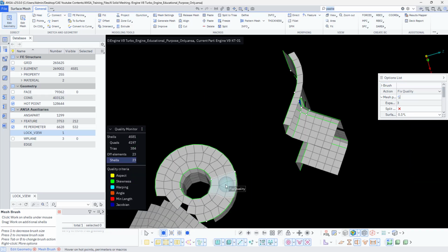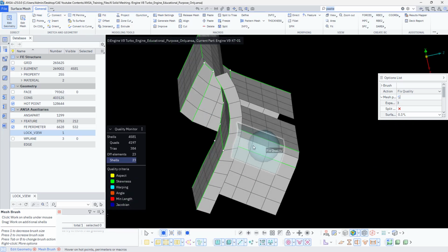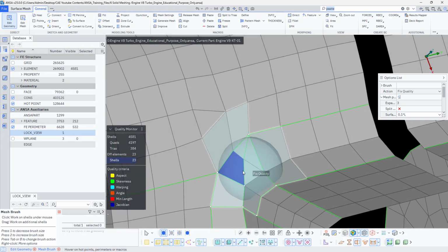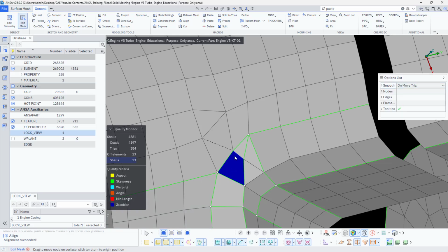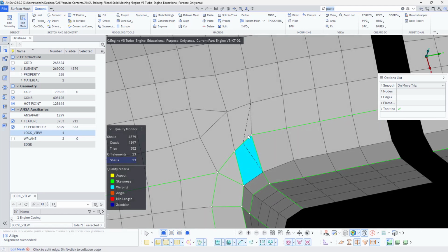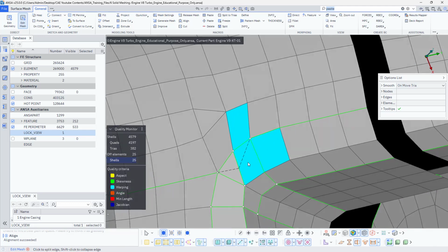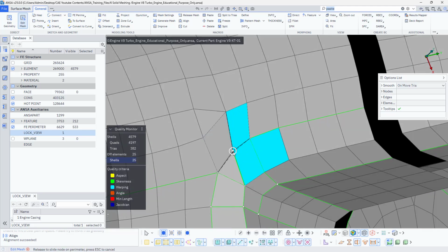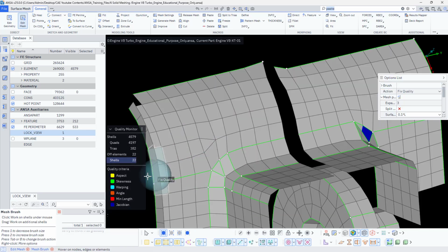Actually, yeah. Here, in this case also, best would be join these two, remove this edge, and here the warp edge. Sometimes we won't keep actually warp edge, so if you remove it, that would be great also. Means I'm just helping you guys to deal with all the kinds of the mesh criteria. Some people simply keep them. Aspect ratio, they don't care. For NVH and all, durability, and also for crash, we need to remove everything.